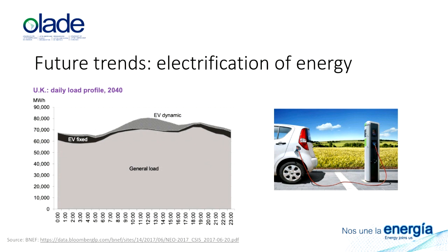But instead of going into that, I wanted to point out that if you look at the curve and the impact here, you see that most of this change is going to happen during day hours, which coincides with the generation curve of solar PV. So this is something that's actually good, because as the demand increases on day hours, we can make the most of solar generation, which is right now dominating the distributed market.